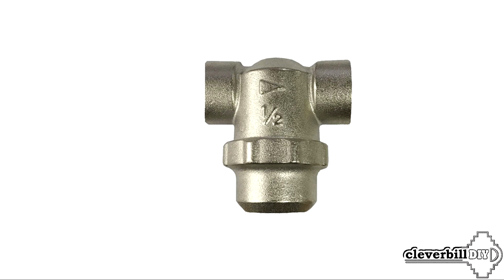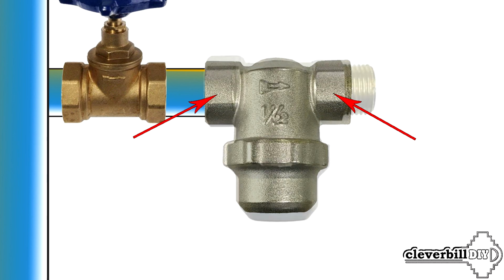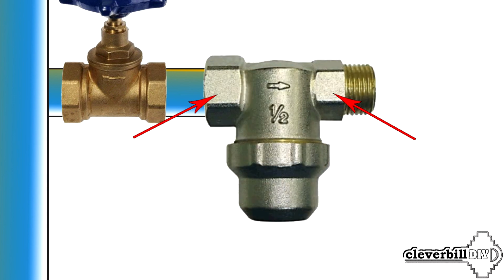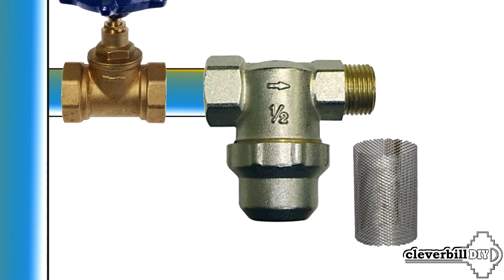A mechanical cleaning filter, or mud filter, is usually installed immediately after the main shut-off valve located at the entrance to the room. The filter is a small housing with a flow direction designation. The body, on both sides, has a connecting thread, which can differ in diameter. The thread can be either internal or external. Inside the filter housing there is a mesh. The mesh, depending on the configuration, can have different transmission capacity.